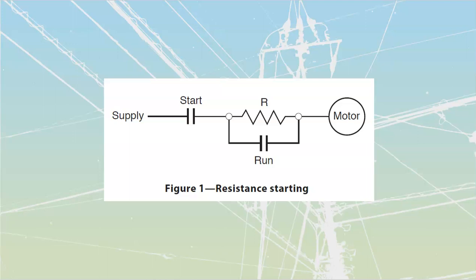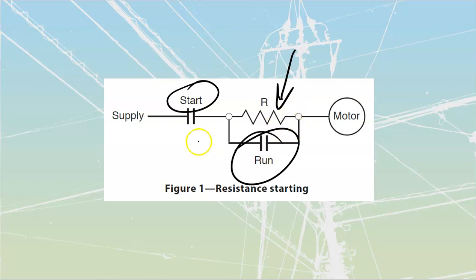Either it's going to be a resistor or a reactor, so this component could be changed to either one of them. We don't know which, but it doesn't make much of a difference to us. Ultimately, it's going to be placed in the same manner. And over here, we see that we've got, once again, two sets of contacts. We did that timing diagram in the previous video where we took a look at the difference between open transition and closed transition, and where we said that we are going to have start and running energized at different times. In some cases, we are going to have closed or open types of transitions.